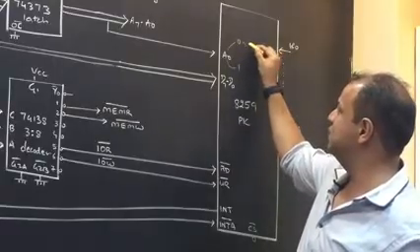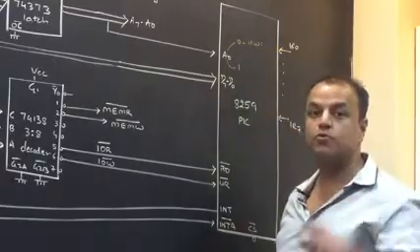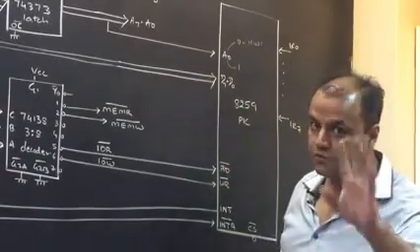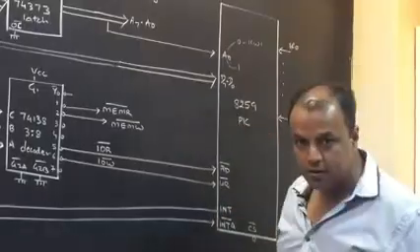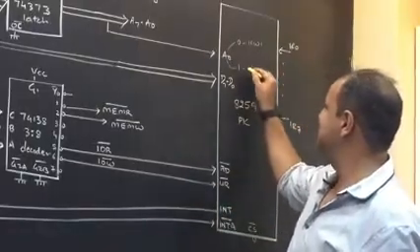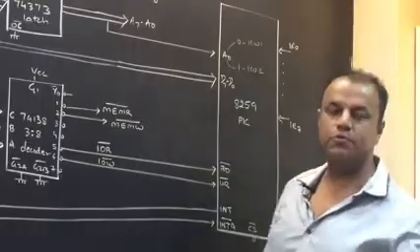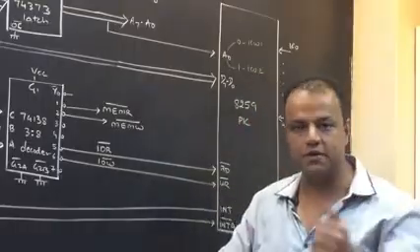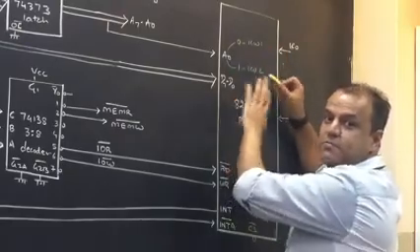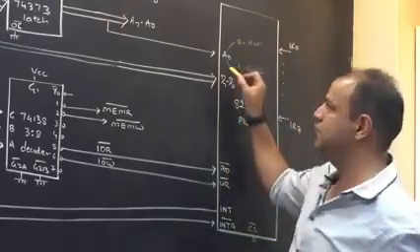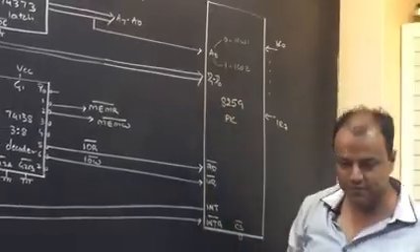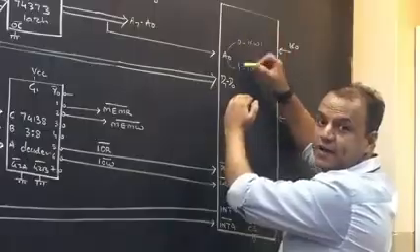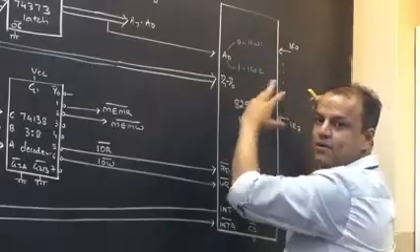If A0 is 0, the command is ICW1 or OCW2 or OCW3, identified by the central bits of the command, the 4th and the 5th bit. I have taught you that. Remember? And if A0 is 1, the command is ICW2 or ICW3 or ICW4 or OCW1, depending upon the sequence in which they have occurred. First it's ICW2, then ICW3. I've taught you that also. So you know what is the role of A0. The job of A0 is to identify the command. So whenever 8259 gets a command, it side by side looks at A0 to understand which command it is, and that's how it interprets the command.